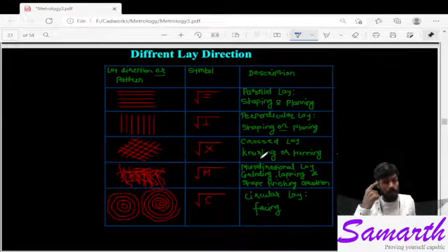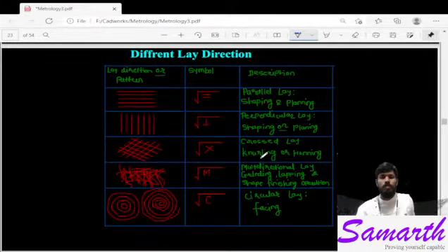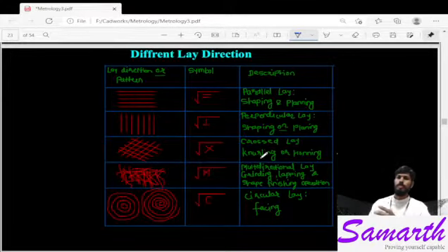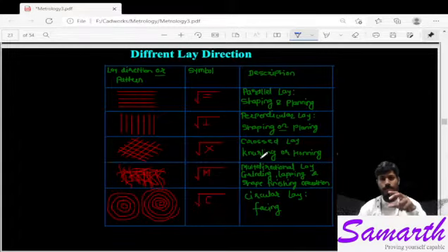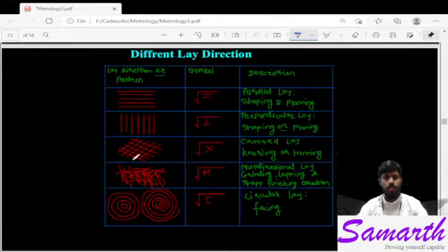Honing, you may see in the machining of the cylinder of an IC engine, for giving smoothness and proper shape to the inside diameter of the IC engine cylinder. Then you may see such a knurling type of small texture. Not exactly knurling, as knurling has a very large depth or thickness.